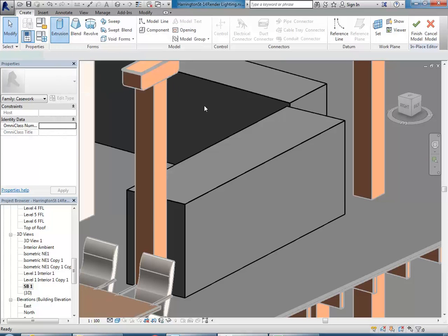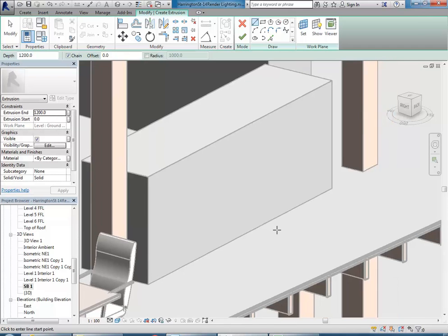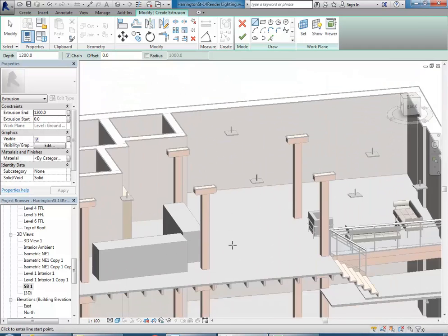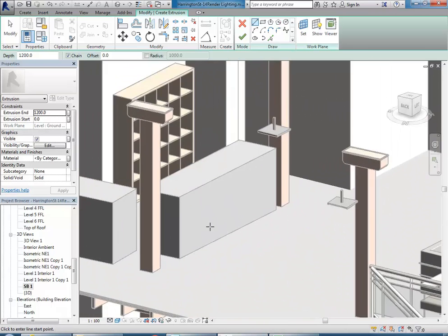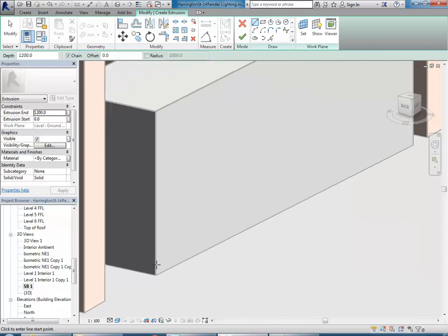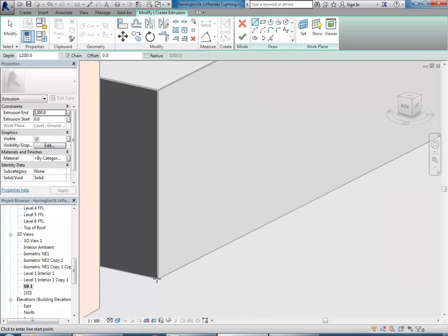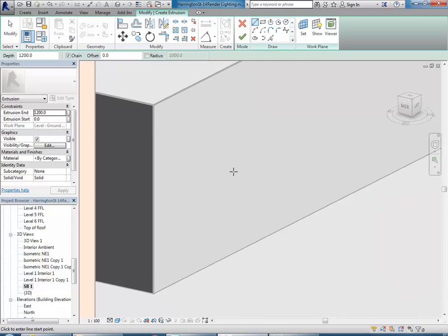So beginning with the extrusion tool, maybe what I'll do is a kick rail. So you know how in bars they have those cylinders of metal that usually sit on the ground and act almost like a kickboard. So that needs to be drawn with just a circle as a profile, but it needs to be drawn in elevation, not on the ground. So all you need to do is change the plane that you're drawing in, and you've got the set option for that.